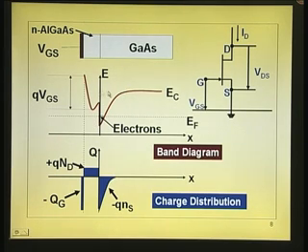The field is in that direction, whereas the energy band diagram here has a minimum, that means the potential is minimum there, which means the electric field is 0. Okay. d phi by dx is 0, and phi is minimum. So, d phi by dx is actually the electric field, but throughout the region there is electric field. You say that because the energy band diagram is bending throughout.